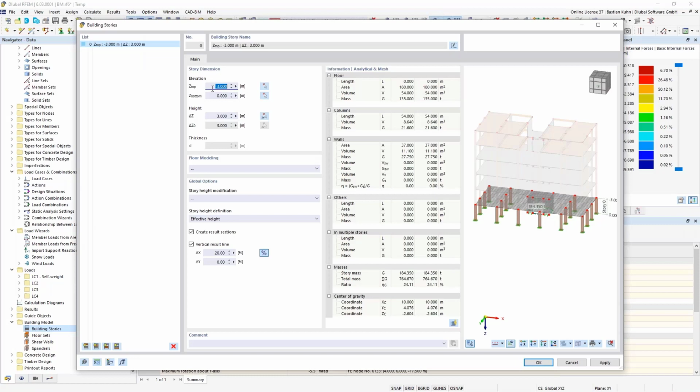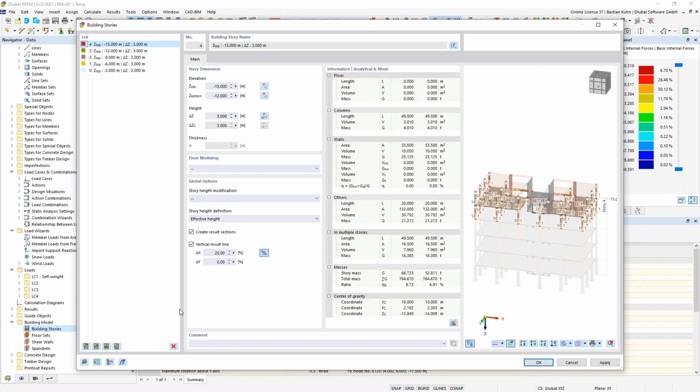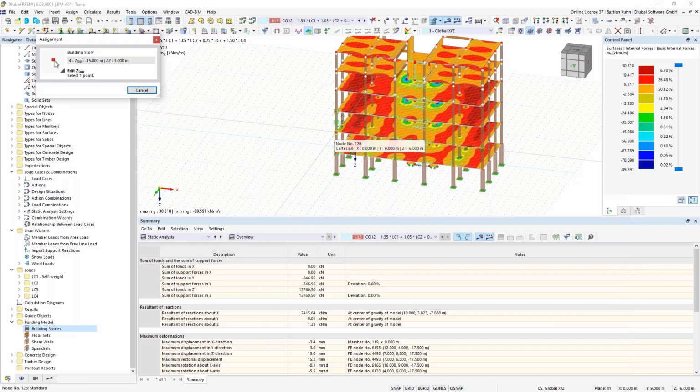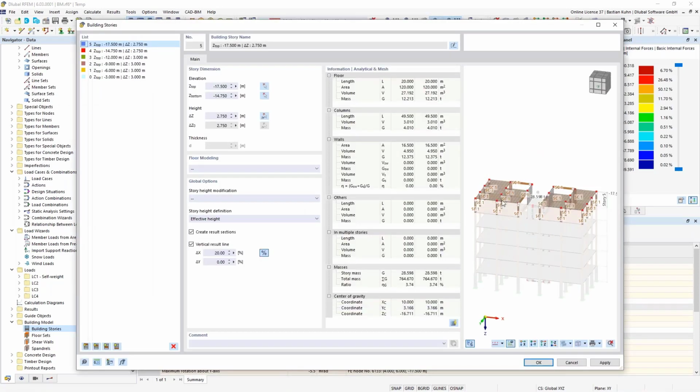Okay, first elevation is -3 meters. And now we can more or less automatically arrange all the other stories. You see now that the 5th floor has a different Z coordinate. I need to pick it again in here. And yeah, then use the last floor more or less automatically. Okay, this I can do, or this I've done now.